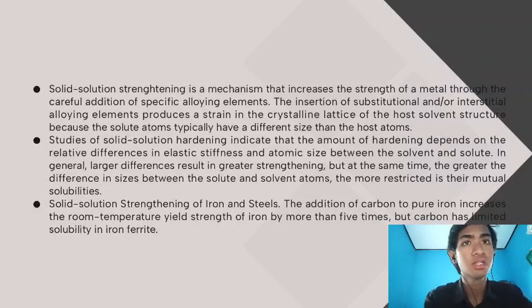As a result, a moving dislocation is either attracted to or repelled by the solute. However, both situations result in a strength increase. When the dislocation is attracted to a solute, the additional force required to pull the dislocation away from it is the cause of the added strength. If the dislocation is repelled by the solute, an additional force is required to push the dislocation